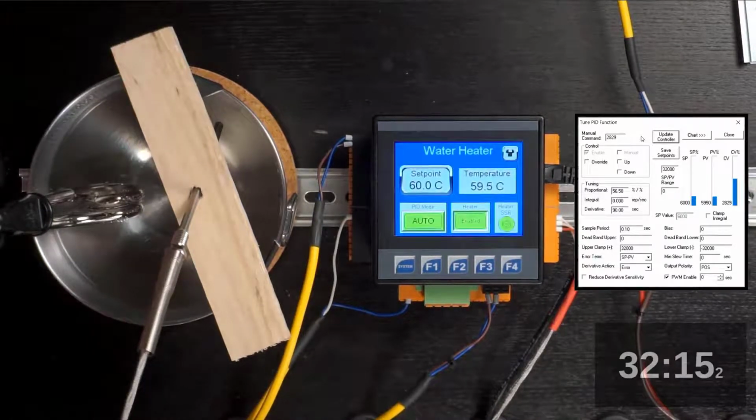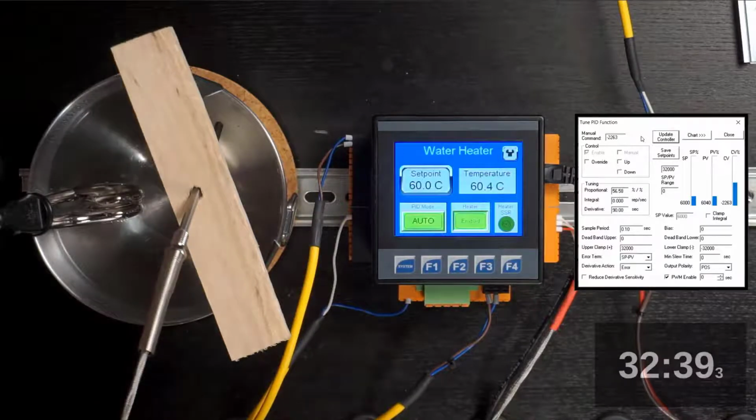It doesn't appear to be helping. If anything, it appears to be taking it the other direction. So I'm going to let it go up through this cycle, and then I'm going to try reducing it by half. So it was at 45 originally. I doubled it to 90. Next, I'll try dropping that down to, let's say, 20 to see if that offers an improvement or not. But I'll wait a couple minutes before I do that.